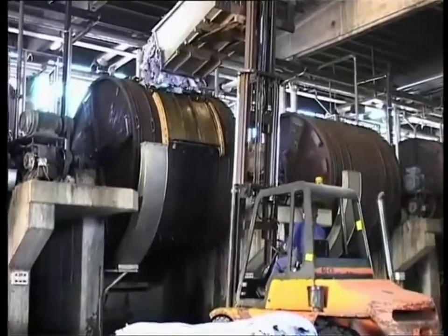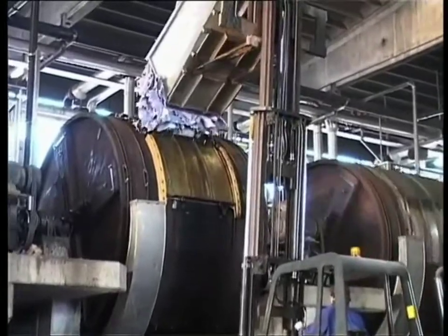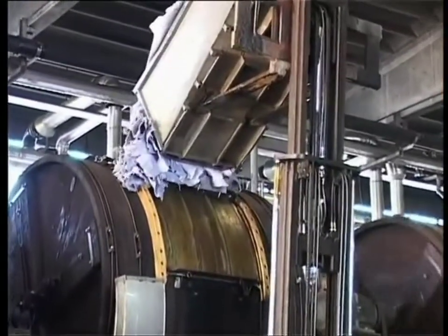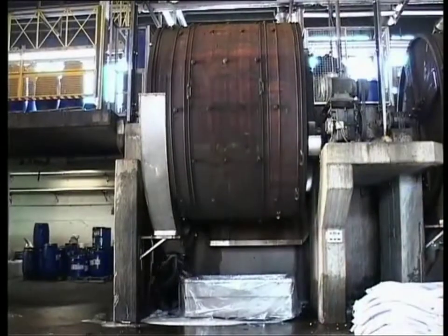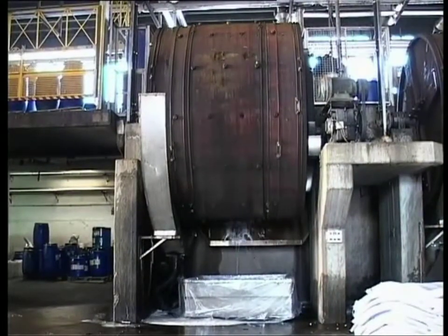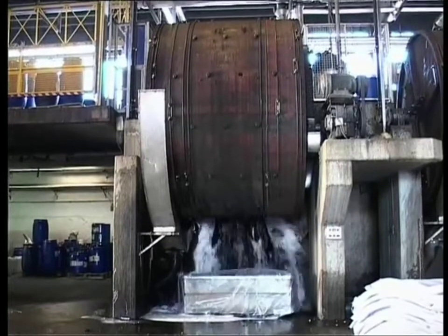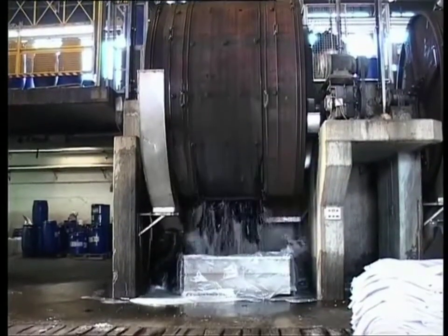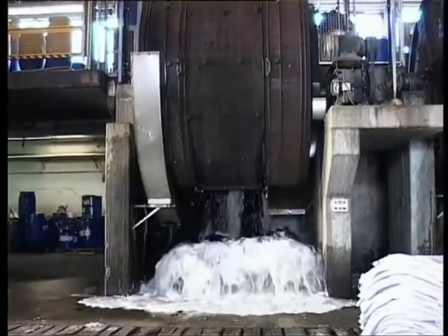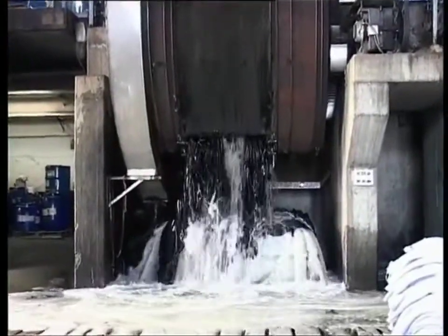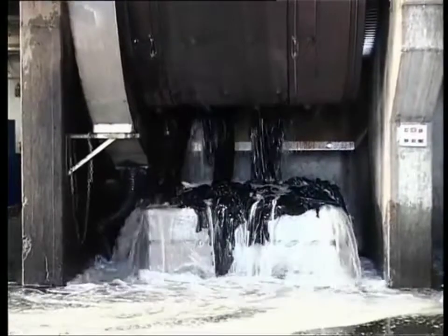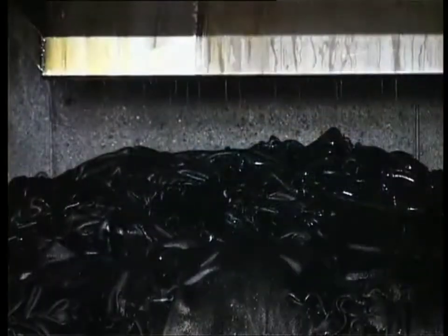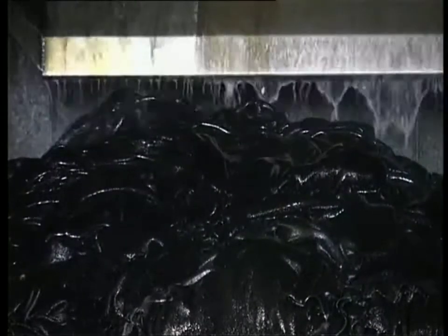The leathers are then retanned and dyed through, literally a further tanning treatment to modify leather's properties. The leathers that exit here are now uniformly dyed. The natural beauty of leather is made even more striking by the wide variety of shades which the modern tanner is capable of producing. The last of the wet operations is the fat liquoring, to grant leather permanent softness, elasticity and flexing resistance.